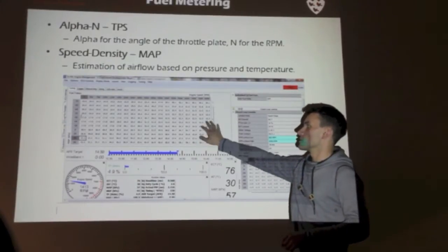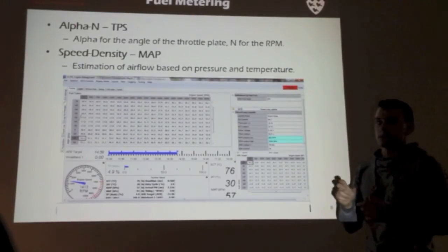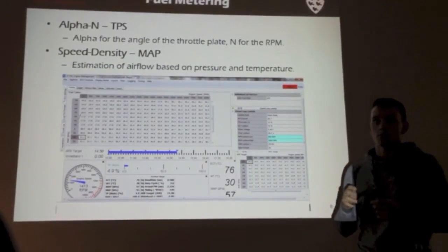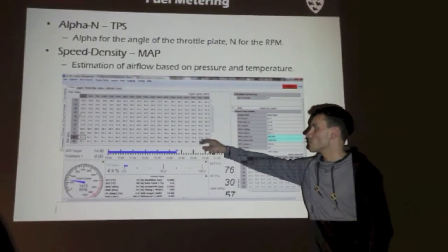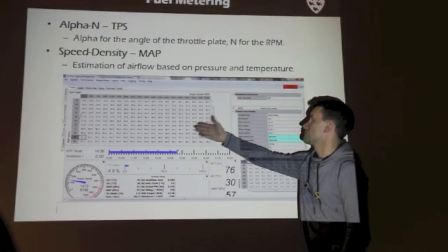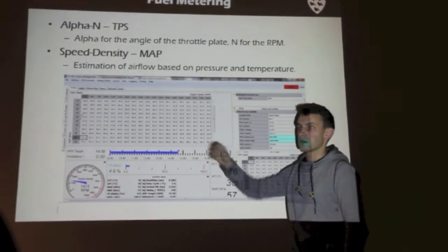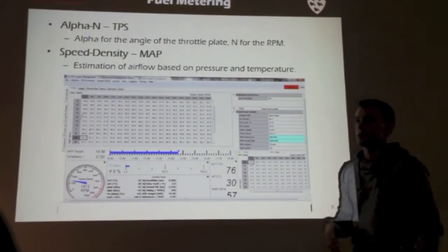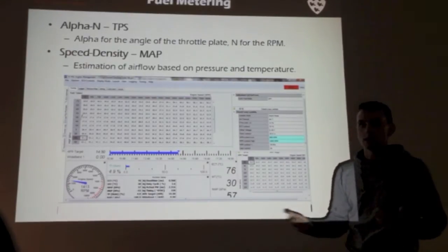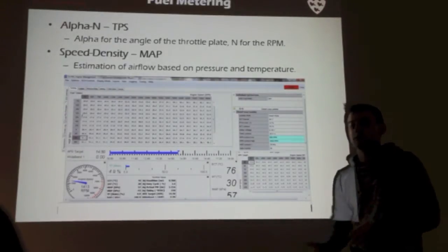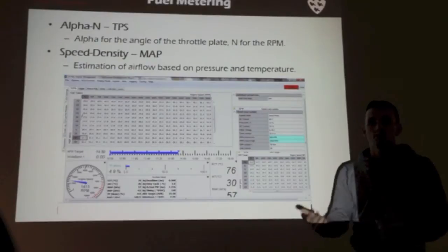These numbers stand for the pulse width that your injector is open for, in milliseconds. As RPM increases, you'd keep your injector open for longer, as in most cases the engine makes more power at higher RPM, so it needs more fuel, since it's getting more air.